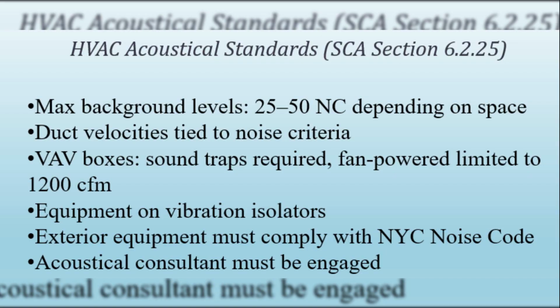The guideline also defines duct and terminal velocity limits, since higher airspeeds can create excessive noise at outlets. Each noise criterion level is tied to a maximum duct velocity. For instance, an NC 35 supply duct should not exceed 1,000 feet per minute, measured 30 feet upstream from the terminal. Round ducts and plenums may be allowed slightly higher velocities, but must remain within recommended ranges.